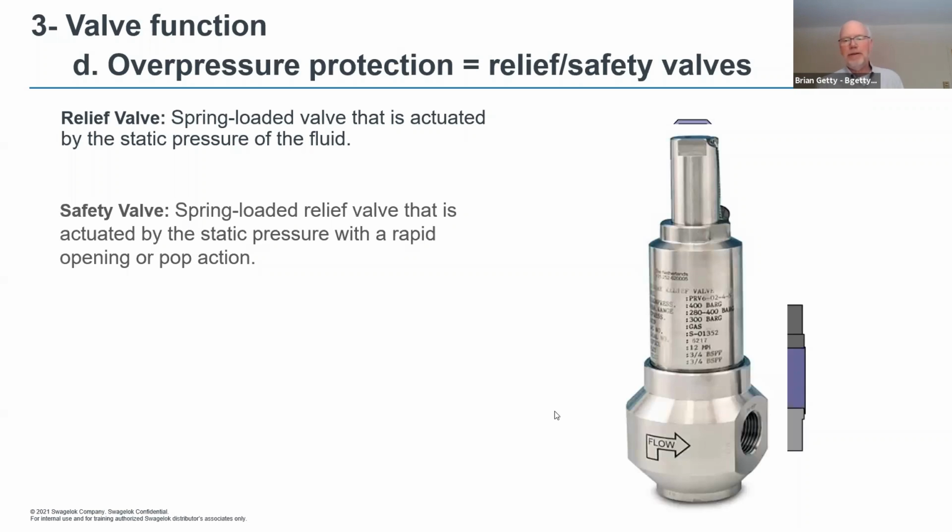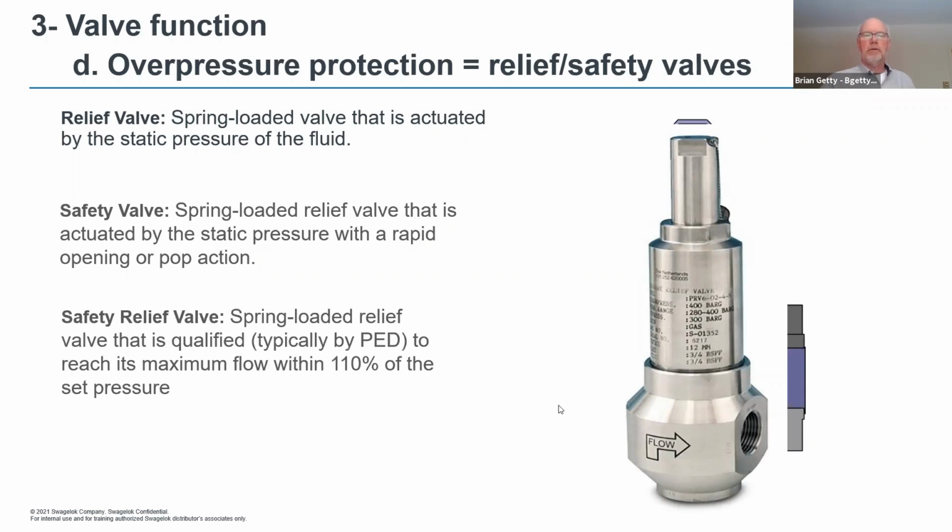To a safety, oops, that's actually the wrong photo. Let me see here. I'm sorry, you got the wrong photo. A safety valve is actually a valve with a large handle to it. With a safety valve, if there is an overpressure situation, the safety valve will pop. Okay, it gives a loud popping sound. It'll pop to an open situation, therefore allowing your excessive pressure to evacuate.